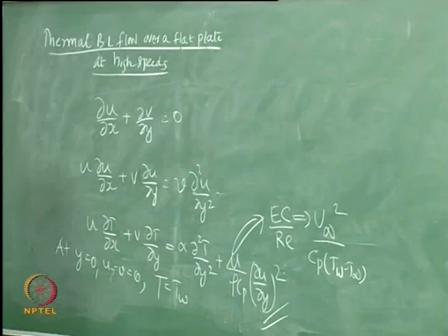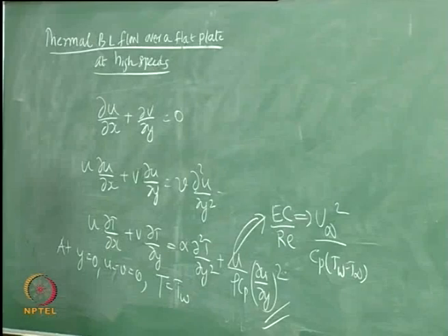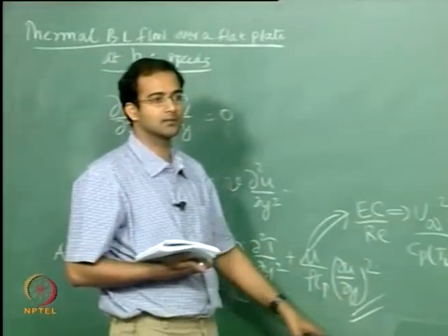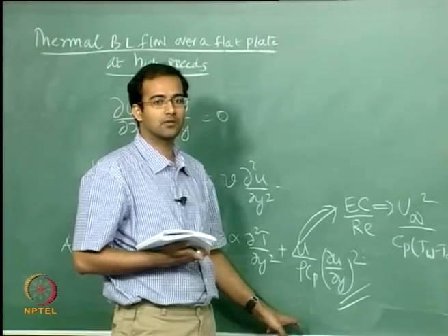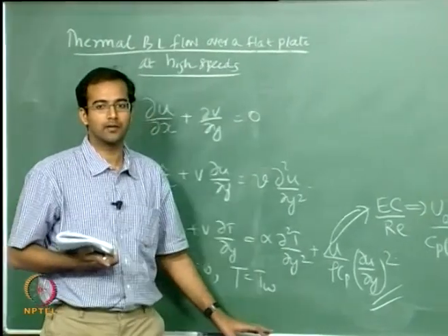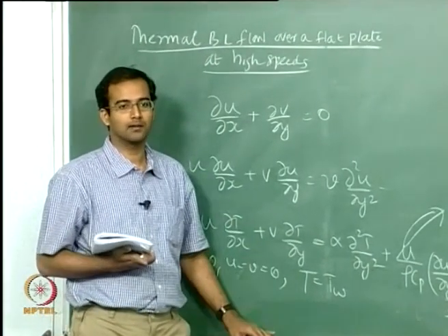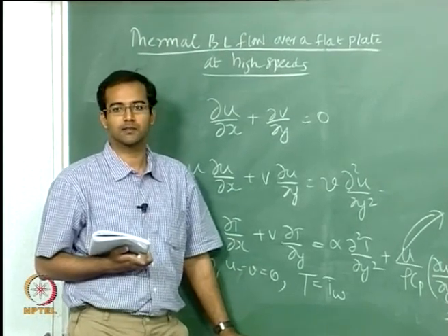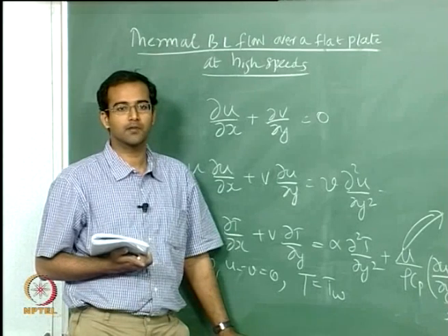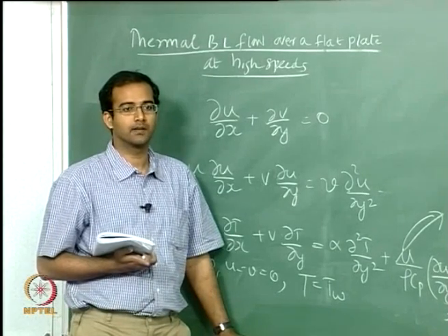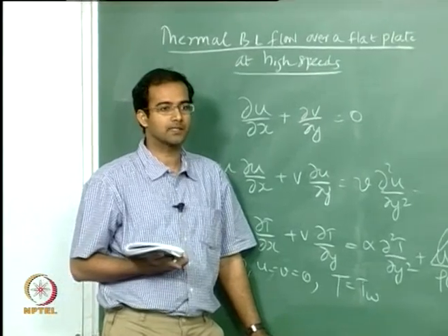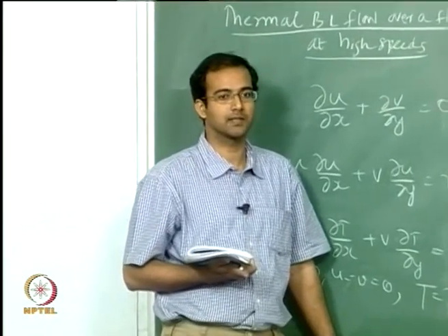That is changing the temperature locally. Because this gradient of course varies inside, there is a local variation of temperature. So even if you maintain an adiabatic wall, you can get a temperature profile if you have viscous dissipation. Therefore for high speed flows considerable effects can be observed, where your temperature will vary from the free stream temperature because of viscous dissipation itself.